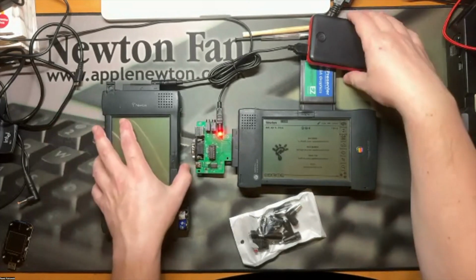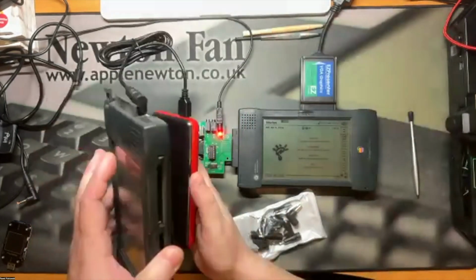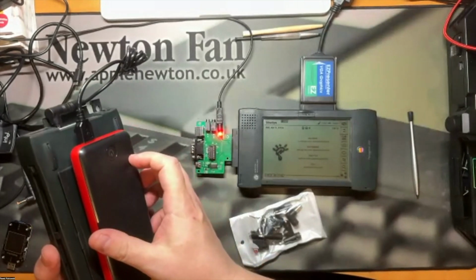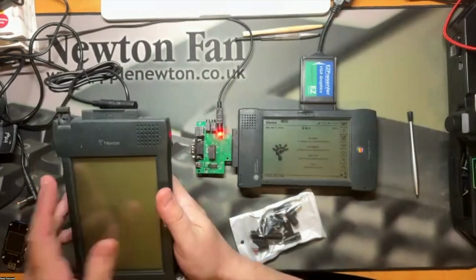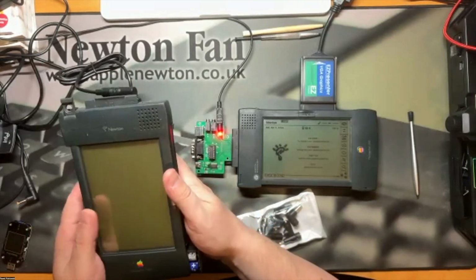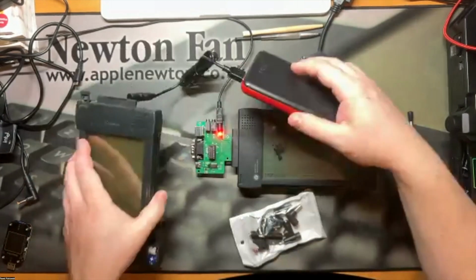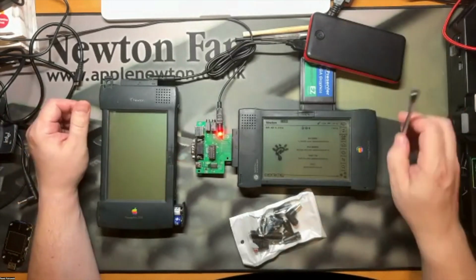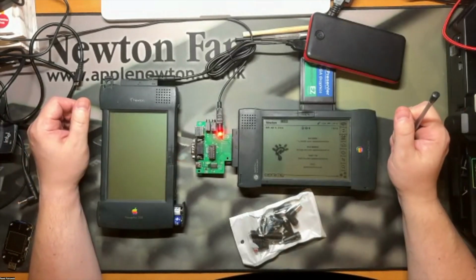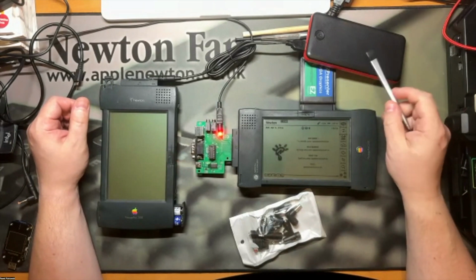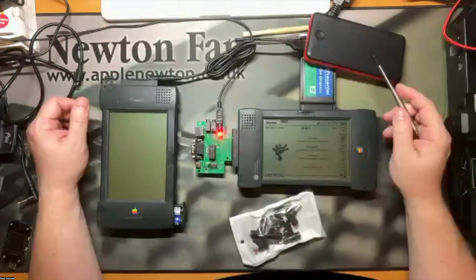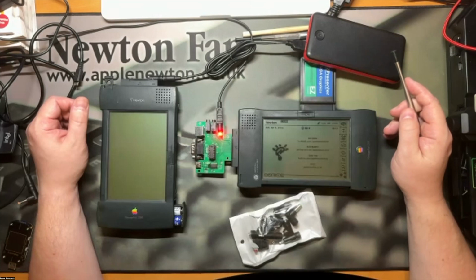And I'm working on a shorter cable and a case so that I could put the battery pack under the Newton and have a slightly heavier device. But my test was with the Wi-Fi card. The Newton itself draws just 80 milliamps, so it's not much. That power bank is 10,000 milliamp-hours. So you can do the math, it's probably more than a week of non-stop working.